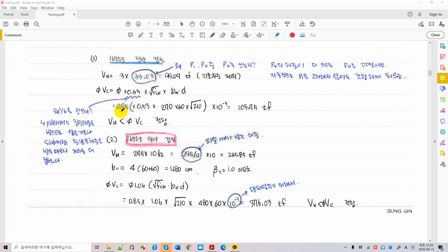As this, right? So I'm going to give you a little thinking point. Take a look at these coefficients over there. We use a 0.53 instead of 1 over 6. So we have increased the one-way shear pile capacity a little bit because we have concentrated loadings on this pile cap instead of a distributed load as we used for slabs and shallow foundations. So we're going to have a little more benefit from this change of coefficients.